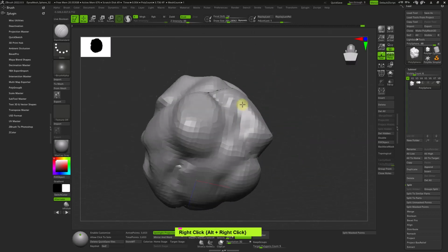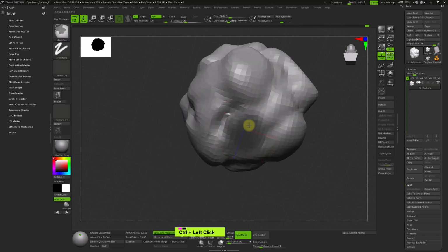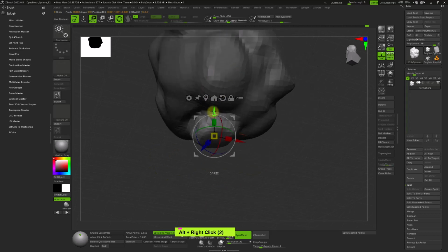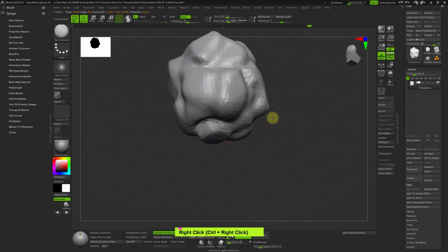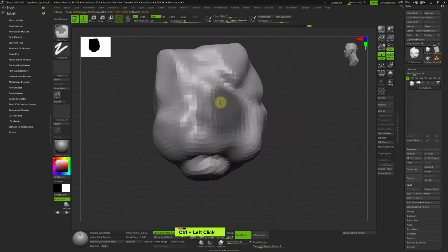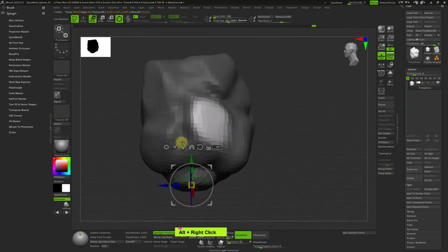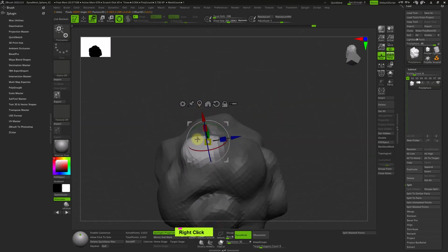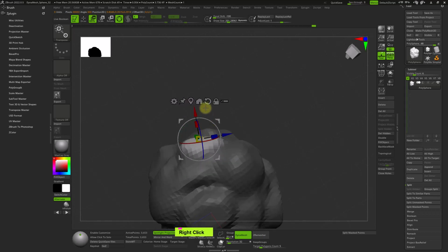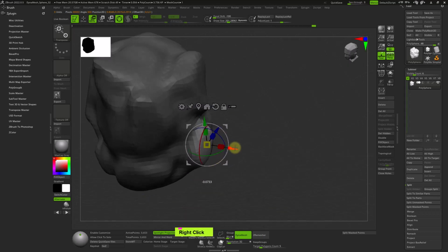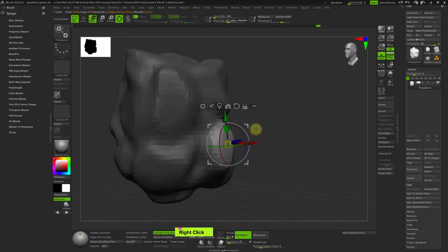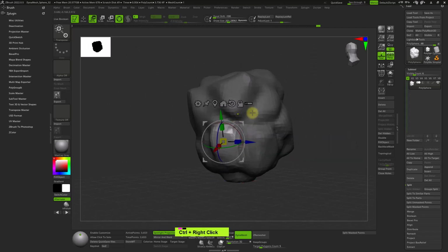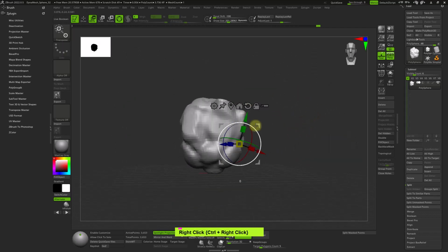That's looking great. Here at the bottom, I think we can mask it around, invert the mask, and just pull. So I'm going in here and pull. This is another technique that you can use. So mask out an area, invert, and just relocate. If you're holding Alt and clicking on a surface, that will actually pick up the surface normal and align your 3D gizmo. So that's a neat little trick that you can use. And what I like to do is just tilt this around, push in, things like that. So this is one trick I like to use.